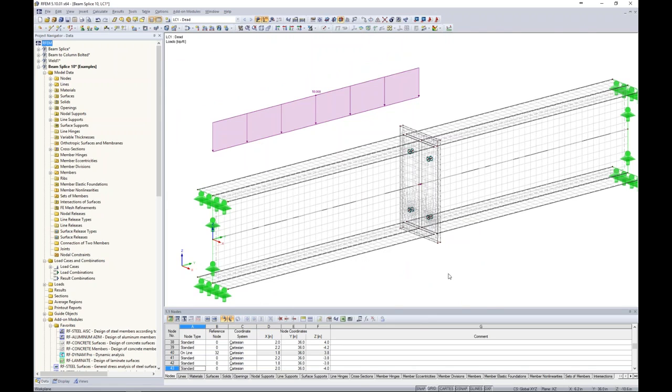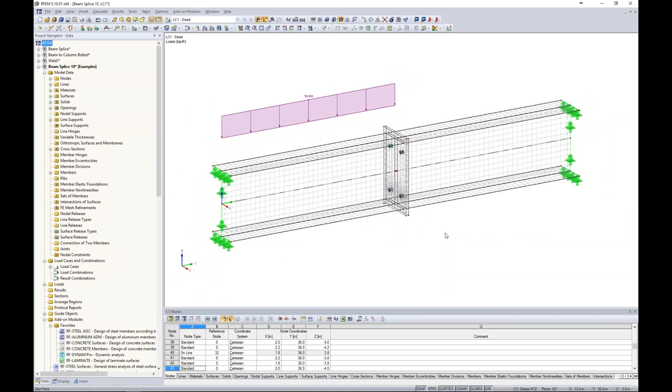Now there is an iterative process with this. You can continue decreasing your FE mesh size smaller and smaller and smaller, and sure, your results are only going to be more accurate. But at some certain time, you're going to be increasing your solution time to be very high in comparison to how much your results are actually changing. So get a better feel for this as you begin to model in finite element software more and more.